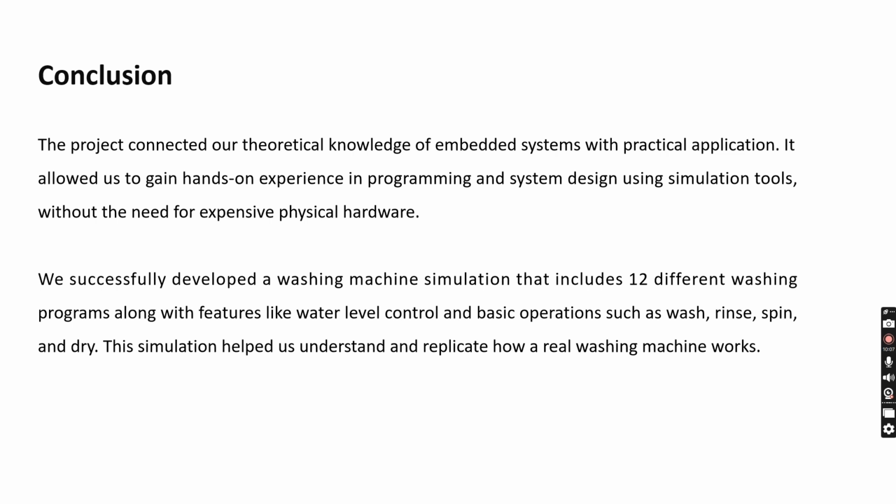The project includes features like multiple wash programs for different needs, real-time updates on water levels, the ability to start or stop at any stage, and easy-to-view programs on the LCD. I also faced a few challenges like managing time delays between cycles in code, reading keypad inputs in a busy system, and showing correct information on the LCD at every stage. To solve these, I used timers in code, careful keypad scanning, and tested each screen thoroughly.